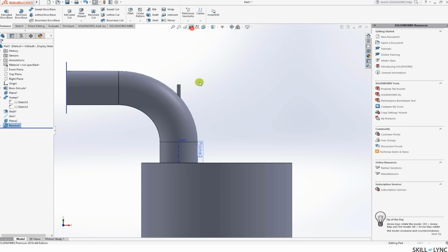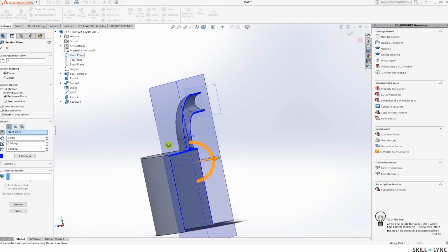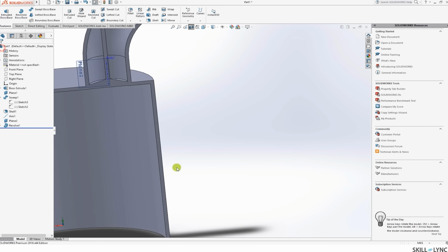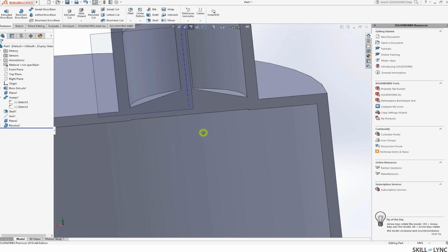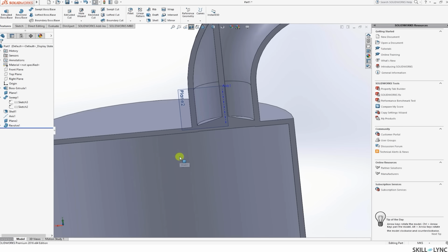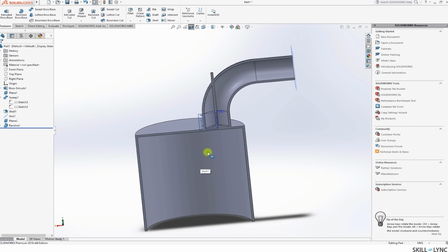The only way you can see that is by doing a cut section, and you can see that since we have drawn the valve very tightly, it's actually merged in. What you can actually do is, when you are creating the valve, create it in such a way that you push open the valve a little bit, and you can basically use smart dimensions to have the valve open at different intervals. And I think that is something that you should be able to figure out. Once you have created the 3D model, make sure that you are able to move the valves by 1 mm, 2 mm, 3 mm, and so on. Okay, because that's part of your challenge.